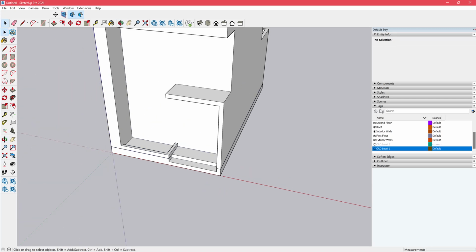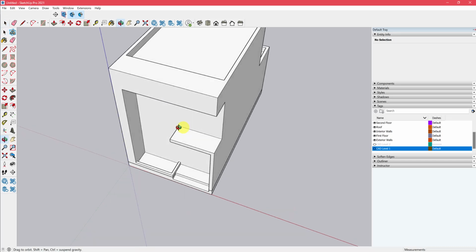Okay, last step, number 11, we'll create the openings for the doors and windows. Very similar to last week. So within your wall group and drawing on the face of the walls, locate the starting points of your doors by creating guidelines for the width using the inference engine to align with the plan. And then all of the doors are going to be 7 feet tall. And then we'll use the line tool to trace over those guidelines. So let's start with the doors.